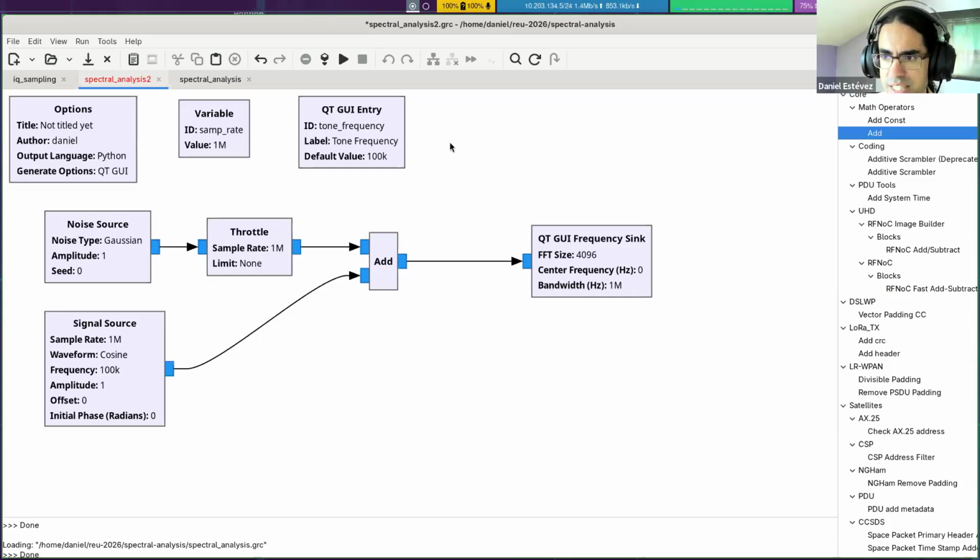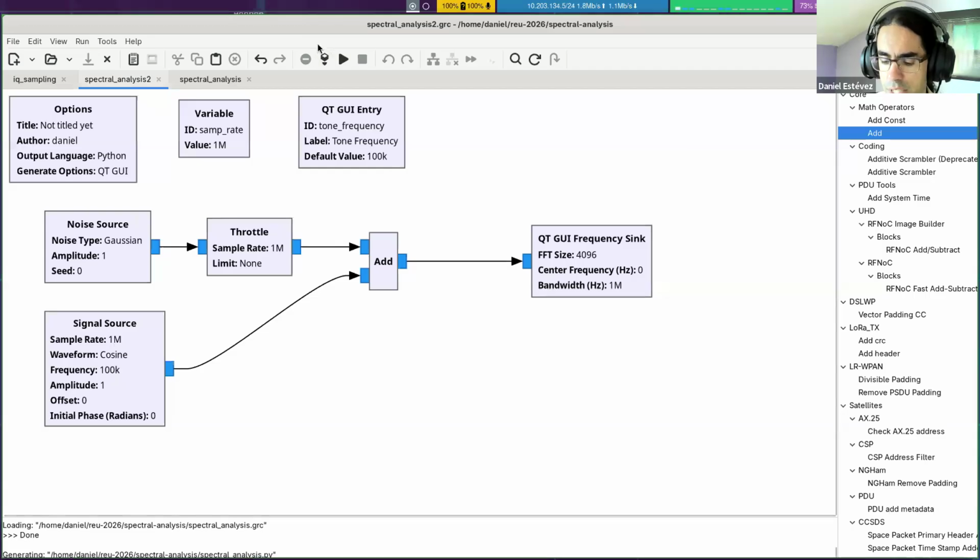And it is something called CN0, which means carrier to noise power measured in 1 hertz. There are other ways of measuring signal to noise ratio, but the issue with other ways is that when you speak about noise power, you always need to define how much bandwidth you use to measure the noise power. Since the noise is wide and present in all the frequencies, if you take a wider bandwidth to measure your noise power, then you will get a larger power measurement.